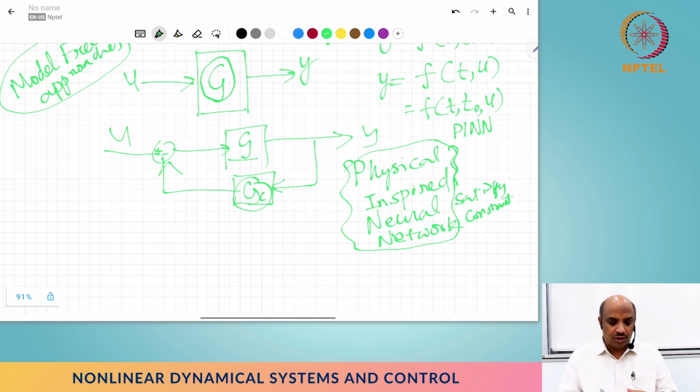In all this, let's say we accept this model free approach. We have some input output, and we design these controllers based on this neural network. The neural network itself, even in the recurrent case, perhaps we can think of as a differential equation or a difference equation, so we have the concept of state. But it's so complicated, it's useless in terms of defining stability and things like that. We actually did not touch the plant that we are trying to control; we are only talking about the neural network approximation for the controller. So we don't know anything about the plant itself. Is there a need for a definition of state? Can we just live with input and output?